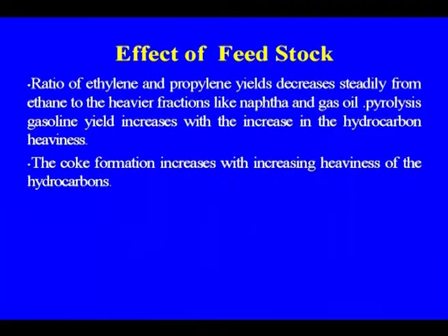As I told you, if you are going for gas oil, you can crack the gas oil and get olefins, but the formation of heavier fractions and pyrolysis gasoline will be more than with the lighter feedstocks ethane and propane. The coke formation increases with the increasing heaviness of the hydrocarbons. The chances of coke formation will be more if you are using the heavier fraction.